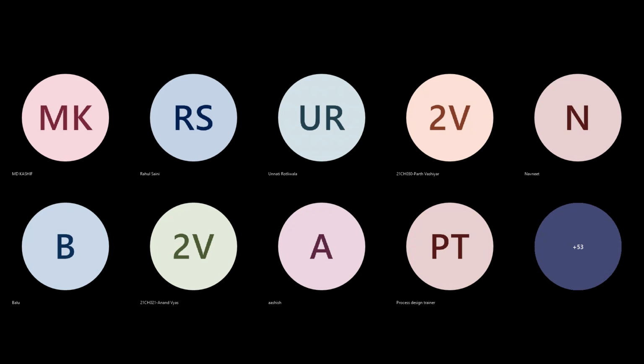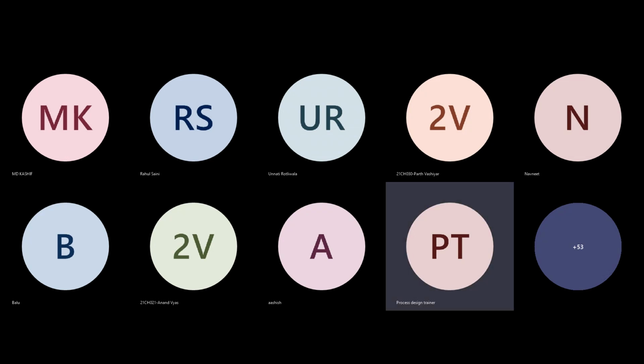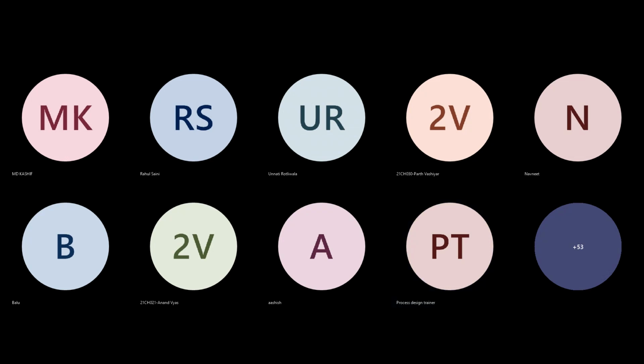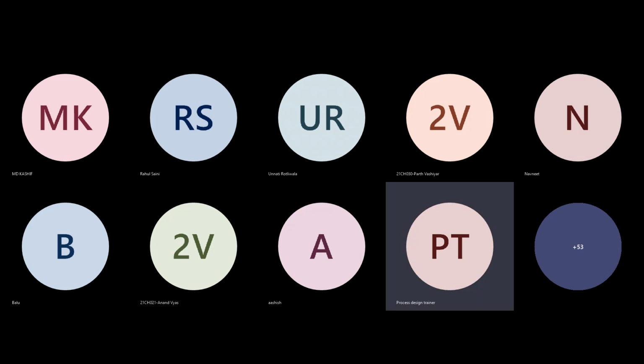People also provide a PSV on the discharge, in order to save the cost. Maybe there are rules, but we have to study. Yes, so it depends. We should not run on shut off, your seal can get damaged, so in that particular case, as a protection, they give a PSV, right? But these are all very rare cases.